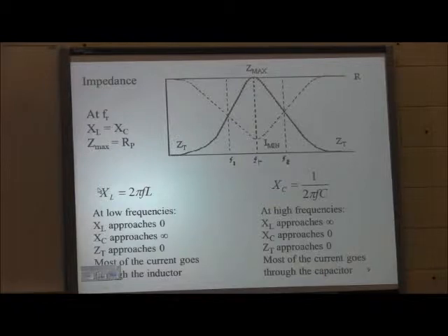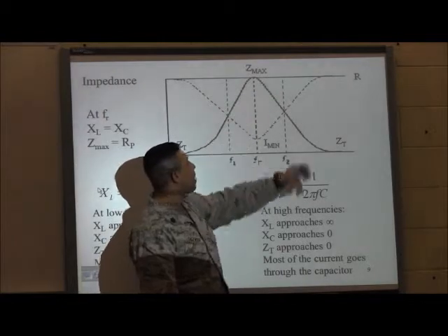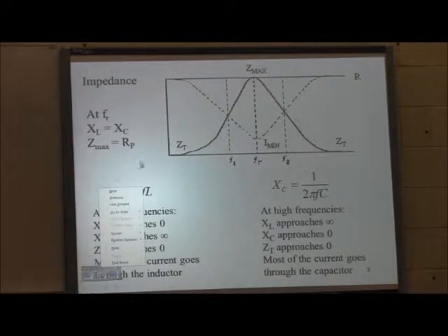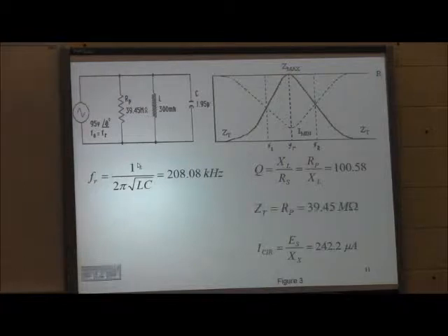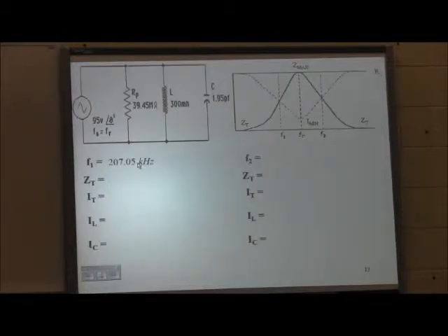So if at resonance I've got a low amount of current, right? Because those two branches have a circulating current. I have low current at resonance, which means that impedance is at its max. Okay. That's really it for the parallel lesson. It's just like the series, except that chart turned upside down. You got the circulating current and you've got R in parallel, which is the equivalent to the winding resistance of the inductor.